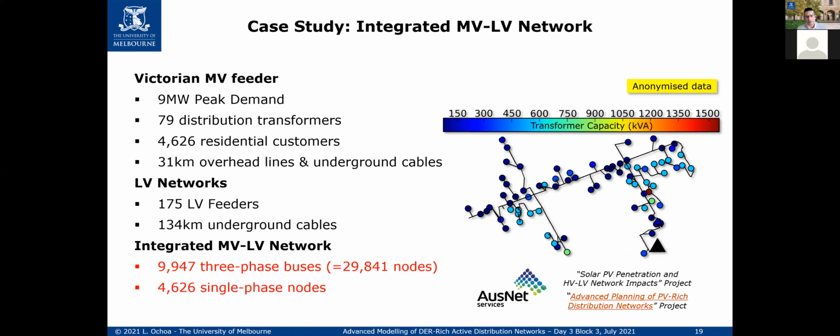So you calculate your optimal settings for PV inverters by playing with the taps as continuous variables, and you solve the problem. But the reality is, what is the setting that you're going to tell your on-load tap changer? Your on-load tap changer is discrete because it's a mechanical device. All right. So these days you have smart transformers in the low voltage that use power electronics, so it doesn't need to be discrete, but still, in the primary substation it is discrete. If we're talking about capacitor banks, it's on and off or different stages. Again, it's discrete.